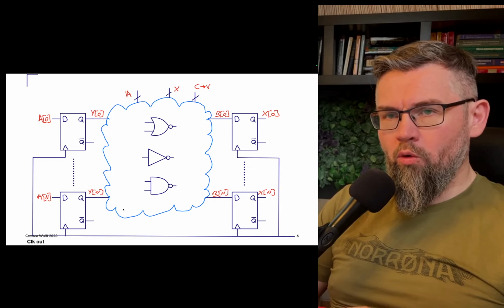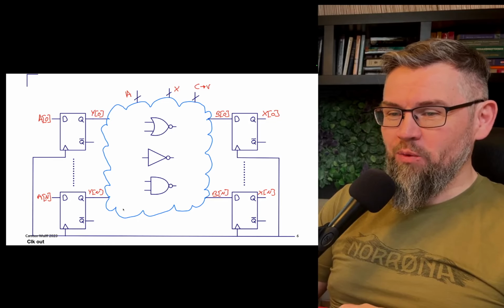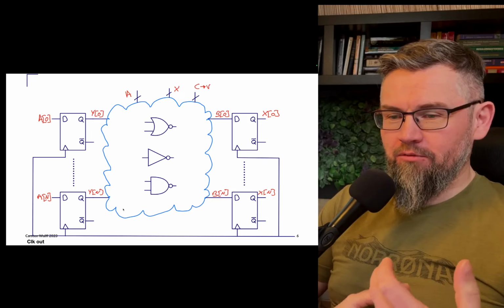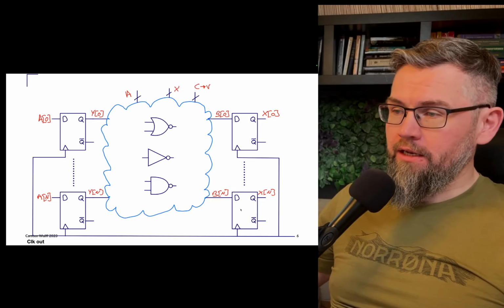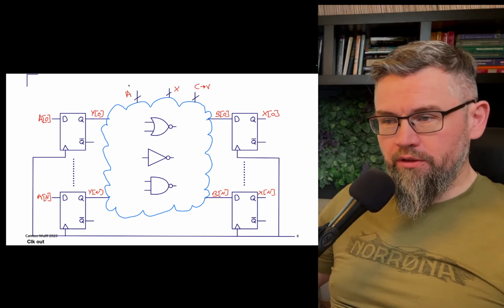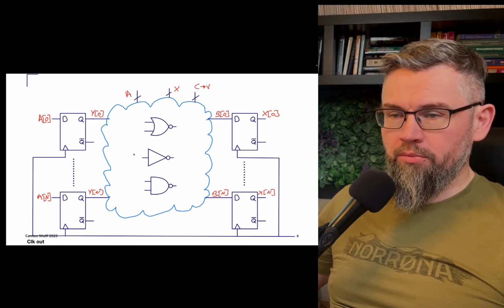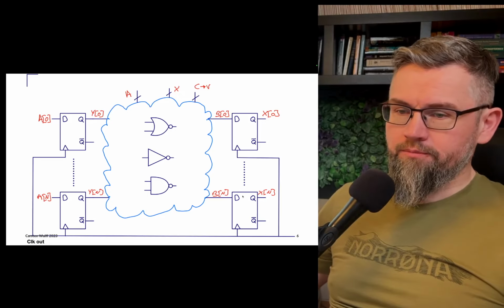So for all digital, well, not all, but most digital systems, we need a clock, because the fundamental idea behind digital is that we have a set of input registers and a set of output registers. In between those, we have some combinatorial logic. So this is your always_comb and your always_ff parts in your SystemVerilog.